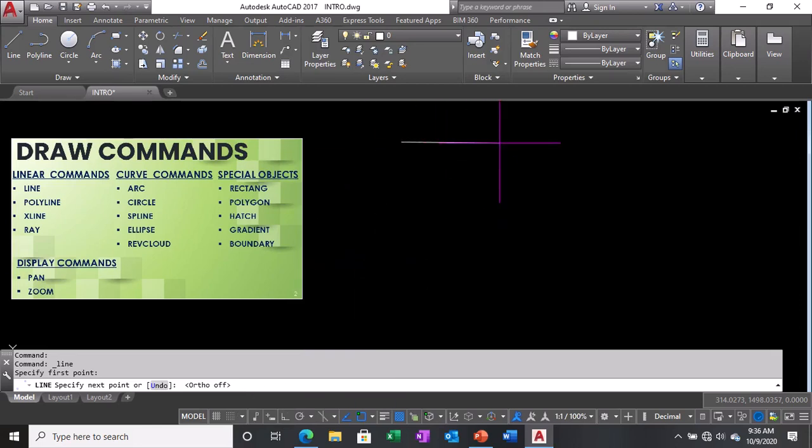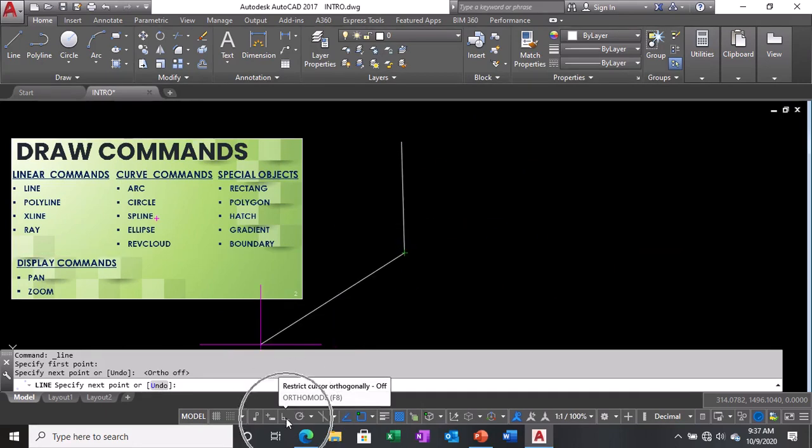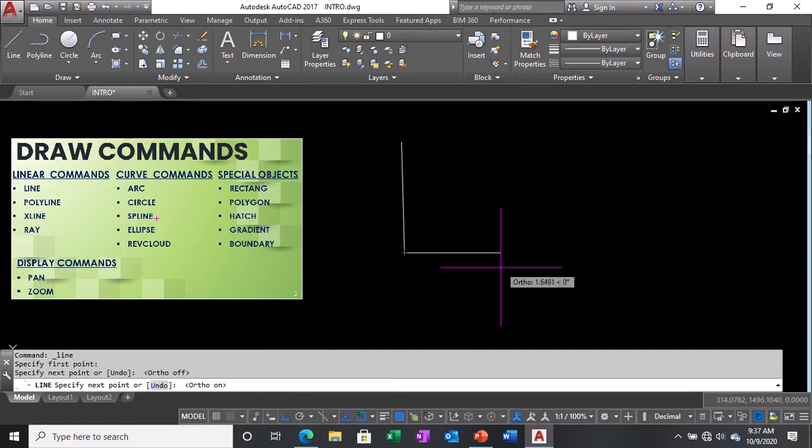I will be picking another point here because you need 2 points to connect, so we can form a single line segment. And then the next one is you are still prompted to specify another point. Okay, so this time we will be doing a straight movement. So you can click the ortho icon dun sa may status bar, or you can also press F8 sa may function keys. Okay, so guide it. You can also specify exact amount, but let us just assume another point and click.